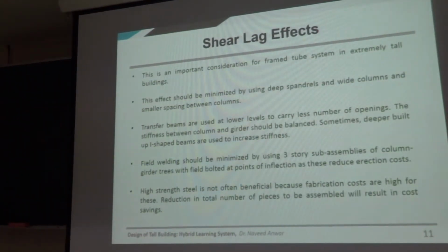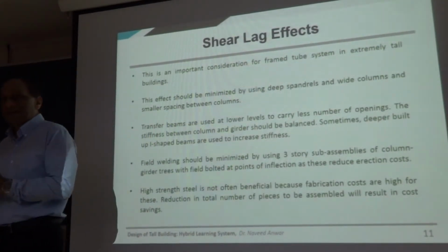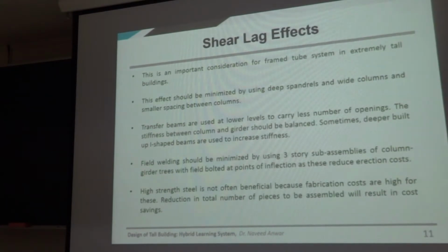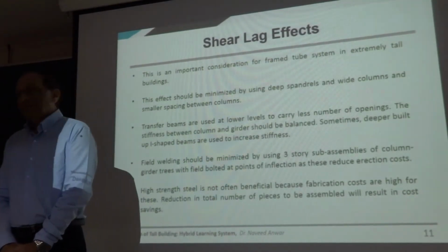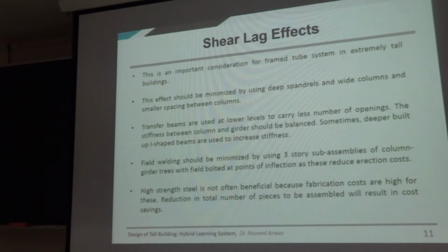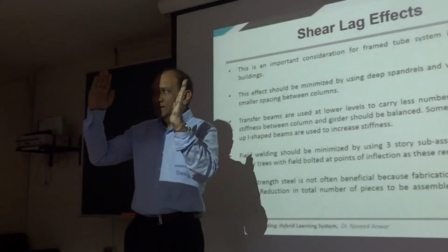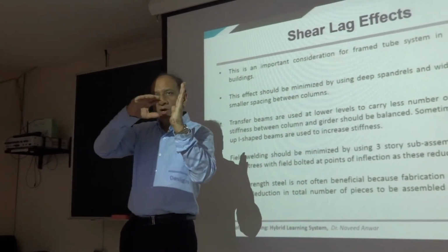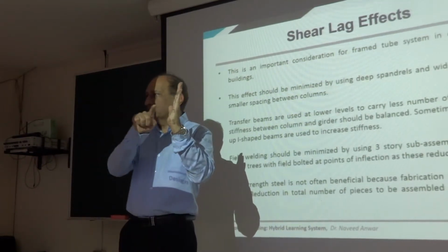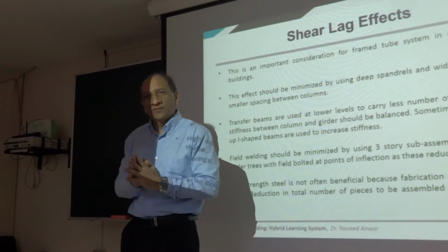These are some other concepts that will come in. I will show you pictures, I will show you things after that, but you need to understand one important concept, especially in tall buildings: the shear lag effect. Shear lag effect is that when the tall building bends, the deformation from one side to the other side is not linearly distributed. They lose some flexibility in between. There's a flexibility of the framing system.